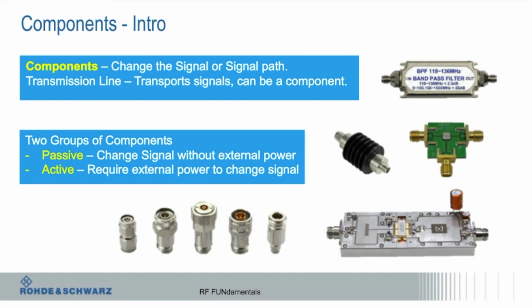You can see the center pin there. Often on a less expensive connector, that's the pin, and that's the thing the pin goes into, and you'll see often this is white. That's a Teflon dielectric. The dielectric material between the conductor and the outer ground shield may be a solid material. The better connectors, metrology grade connectors, are always air dielectric. They're much more precise, defined over a wider frequency range, and have much better performance. So if you're using a VNA, I always recommend using air dielectric adapters.